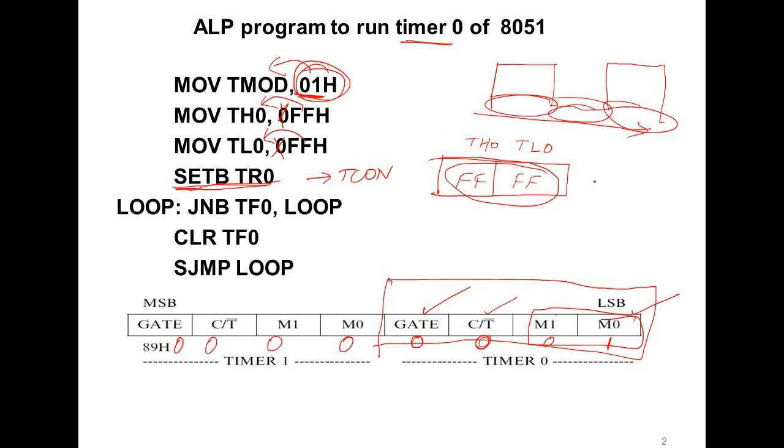From FFFF, this is approximately 64k times. So here, 64k times, right? Once the timer started running, then once the 64k times is over, it becomes 00, right? After decrementing to 00, it automatically becomes FF, because decrementing means what?